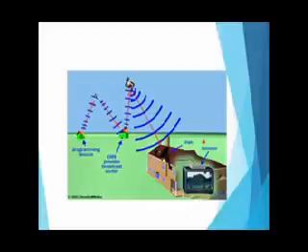Cable TV. Cable TV, sometimes called CATV, is a system of delivering the TV signal to home receivers by way of a coaxial cable rather than over the air by radio wave propagation. The cable TV company collects all the available signals and programs and frequency multiplexes them on a single coaxial cable that is fed to the homes of subscribers.